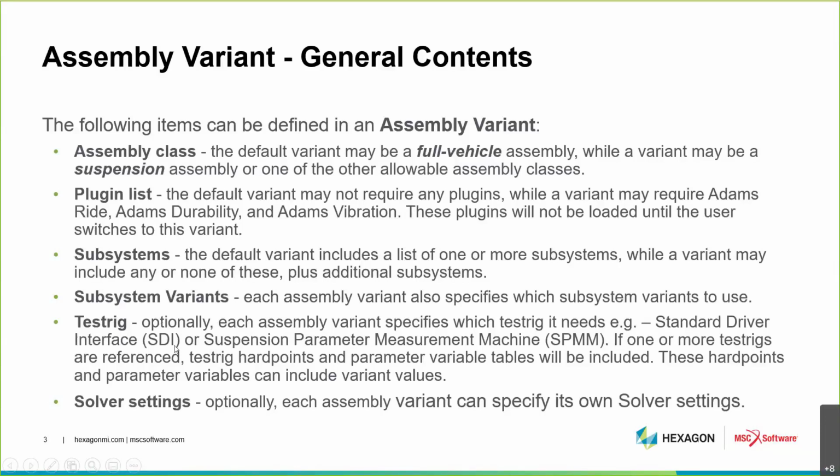The concept of a test rig is something that is important to using Adams Car. And you have the option of saving a particular test rig with an assembly. Examples of test rigs would be the standard driver interface, or SDI, or perhaps the SPMM, suspension parameter measurement machine. And there are others, but the point is you have the option of saving a specific test rig with a particular assembly configuration or not.